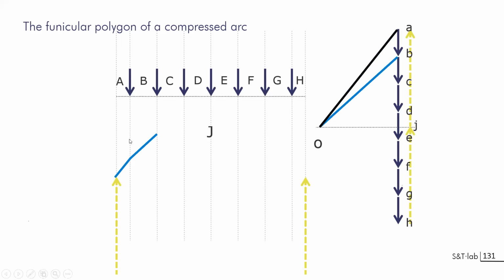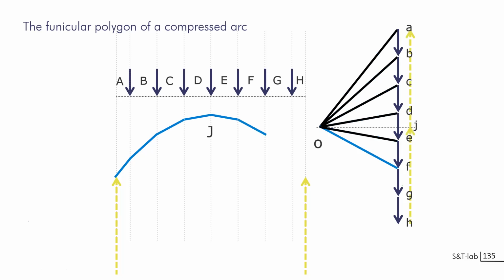The fact is that as soon as you have three lines, you have your first triangle of forces here, showing that this loading here will be equilibrated by two segments of line, two parts of the arch, and you will get the resulting force from this. So you will have a means to draw this funicular polygon very easily, and this will provide you the form of the arch. So this is about design, this is about form finding.